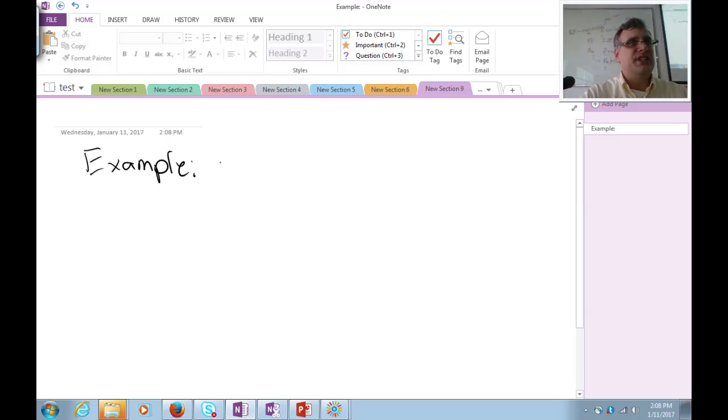You know, in RF engineering, they have these standard cables that you always design to. Standard loads, standard cables, standard inputs and outputs. And you always try to keep at a constant impedance. And the reason is if you've got a 50 ohm cable and you've got 50 ohm equipment and a 50 ohm transmitter, then if you stay with the same impedance, everything is matched. There's no reflection.